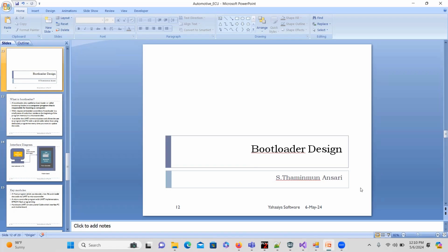After going through all those things, I decided to go for our own design, like whatever we have in the code, that is assembly code provided. It's a little bit hard to understand, but it has a lot of clues in it. I used those clues, and I created an embedded C version of the bootloader, which can do that task. So developing the bootloader alone is not enough.